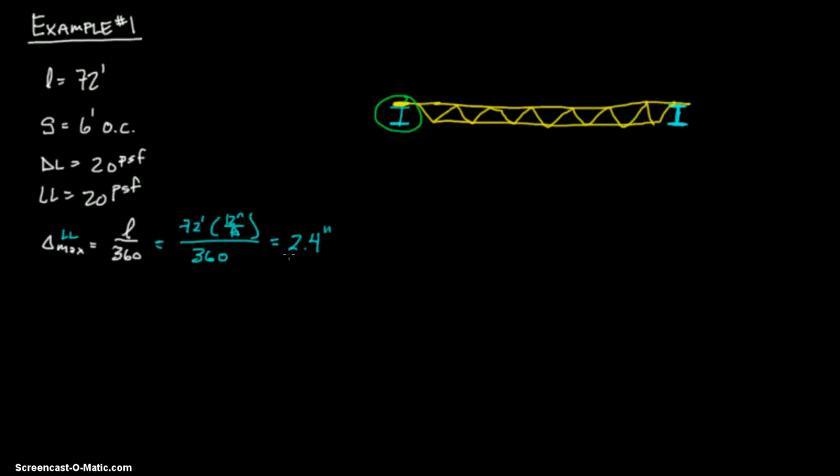All right, so in this case, we're not worried about those beams. We're just doing these open web steel joists, and we know that since they're supposed to be cheap, actually designing these and doing them differently would be difficult. So we just want to figure out, they have these standard lengths, and this standard length is 72 foot. 6 foot on center, what's going to work out?